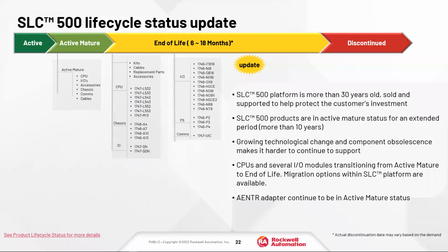So a little bit about SLC. For the most part, all the SLCs are end of life now, and we've got end dates for these, and you can see the different part numbers, the CPUs, the chassis, the IO, power supplies, etc. The SLCs have been around for 30 years.